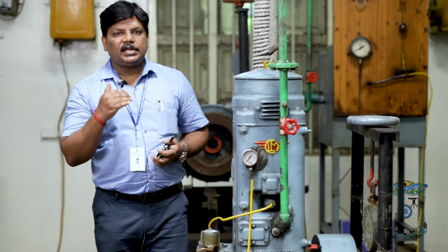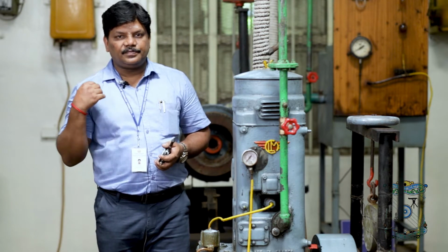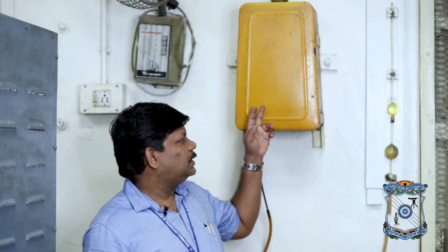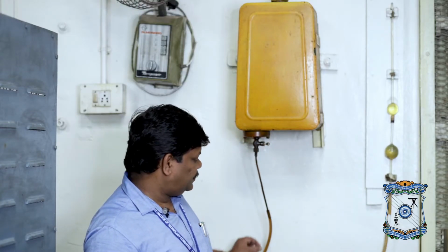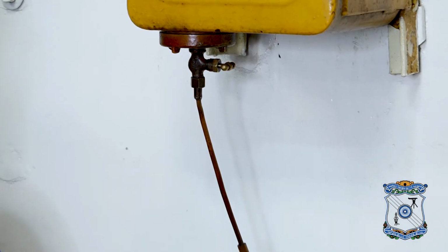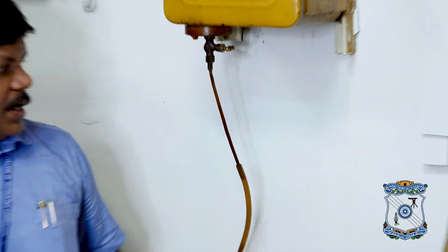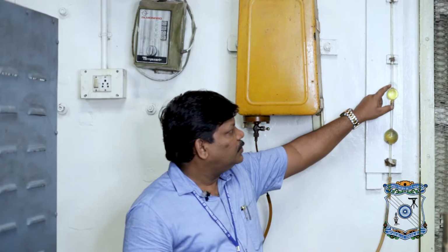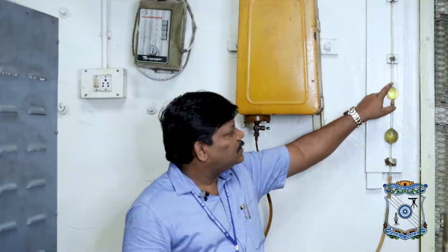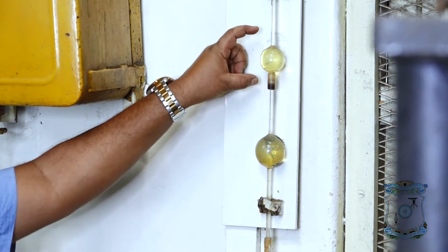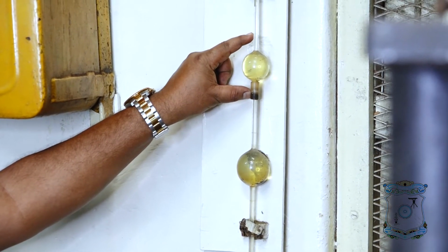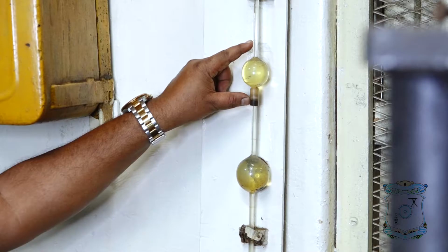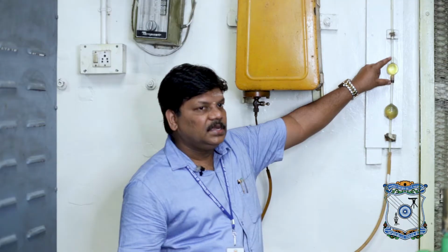The fuel consumption can be measured with the help of the fuel tank. This is the fuel tank. From this fuel tank, the fuel is supplied, and through this tube it is supplied to the engine, and this is for the measurement of 25 cc of fuel consumption. You can see the line. From here to this place, the total amount of fuel consumed by the engine will be 25 cc. From that 25 cc of fuel consumption, you can measure the parameters.